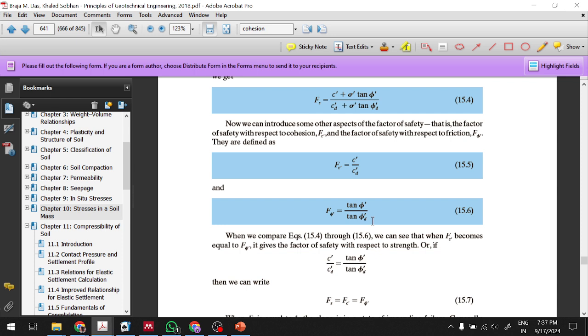But if you think of it, if you have a normally consolidated clay, how much cohesion will it show? It is easily breakable, is it? It is easily sheared when you have NC clay, as compared to when you have OC clay, it is kind of stiffer and it actually shows a good amount of strength, isn't it?